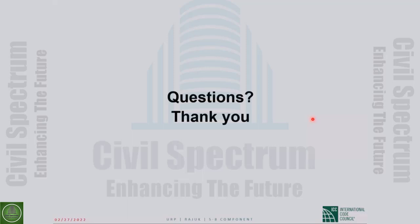If we get the CP performance level from pushover analysis, which is the subject of our Tuesday talk, is it okay for an existing hospital building without retrofit to get CP?